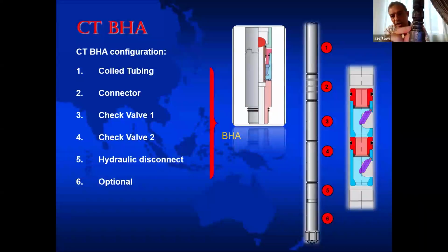And the last two profiles here, where we put O-rings to prevent well pressure and well fluid escaping from here inside the coil, and also to prevent the treating fluid we pump through the coil from going out from here, because we need it to go from the nozzle down there. That's why this internal BOP, they call it a mechanical barrier as well.